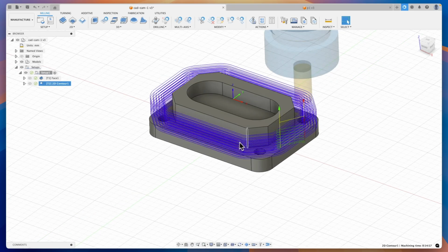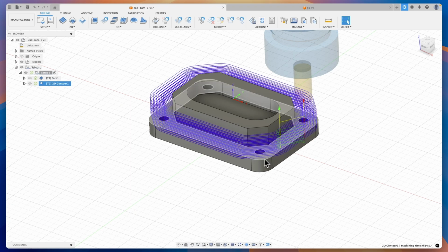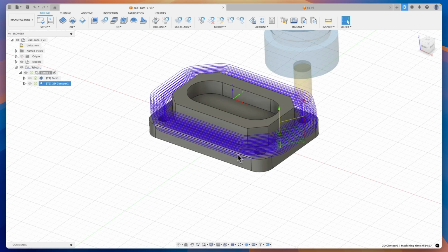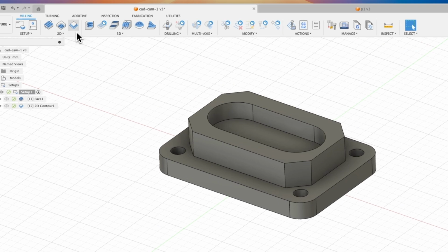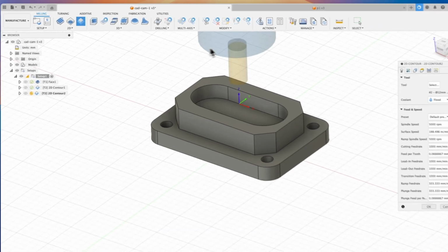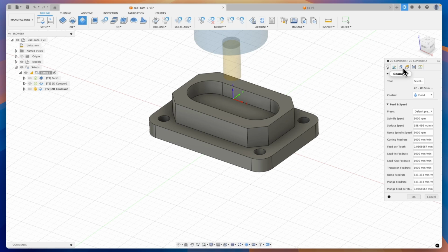However, as you saw in the case of the previous machining, in those initial passes, material was only removed at the corners, and here, in the case of machining over those straight sections, the tool was working in the air. In this case, we can split this machining into two strategies. In the first strategy, we can machine the corners, and in the second strategy, we can machine the contour. We will add another contour machining operation here. I choose contour machining. We will use the same tool and go to the Geometry tab.